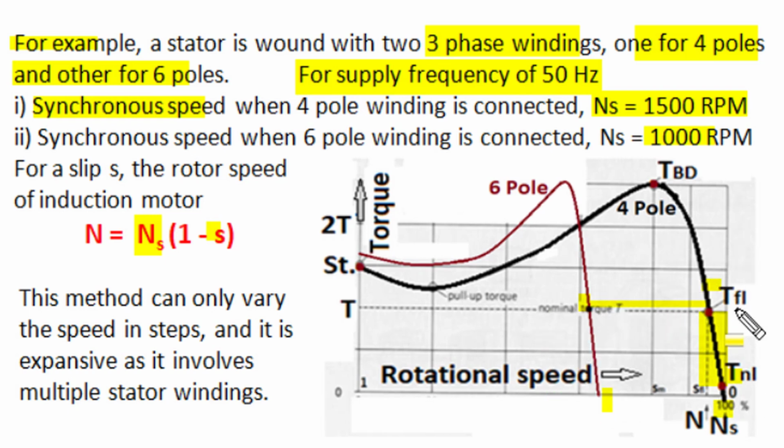So we can change the speed of operation of the induction motor in a step to two different required values, and if a process requires two different operating speed conditions for a certain performance, then the same motor designed for two numbers of poles can be used to perform its duties for two different speeds.